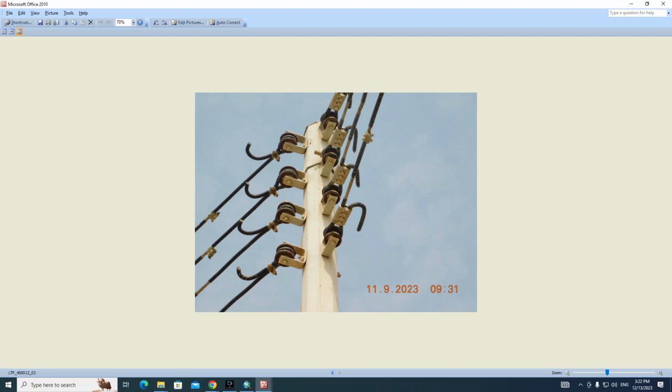I will not place anything, but I will split the line. I will not merge this line with this line, because this one may have a different source and this one a different source. Later on there will be sync and source. If you merge, you will have big trouble filling that attribute, and it will cause big problems for many assets. So be careful about this type. So we can place both the points on the pole, or one line should be away from the pole? No, both lines will be on the pole, but they will split.